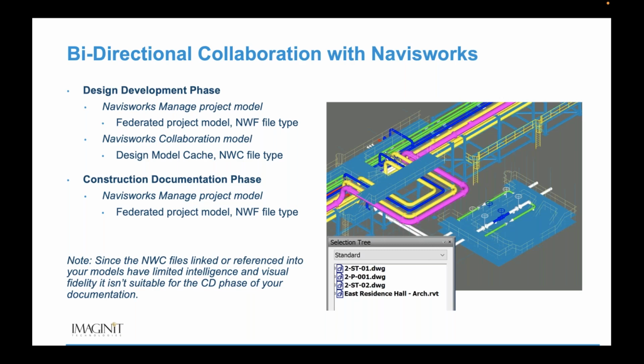So when we're talking about working with the design development phase, where I'm trying to figure out everything that's going to go into that model and where it is, how I route to it, those types of things, whether or not I have collisions or clashes, that Navisworks NWF model, or the federated model, is really going to be the workhorse for that. And as a byproduct, the federated Navisworks model will also create the NWC files representing each of the individual design models that my team might be working with.